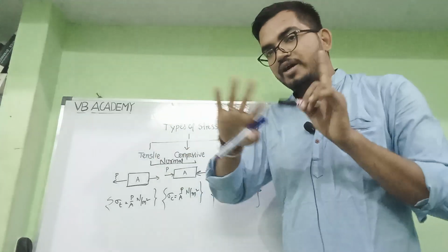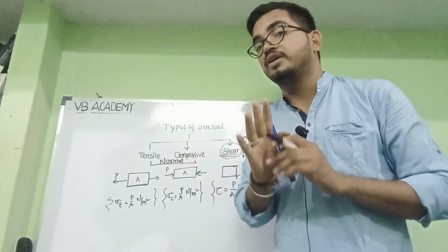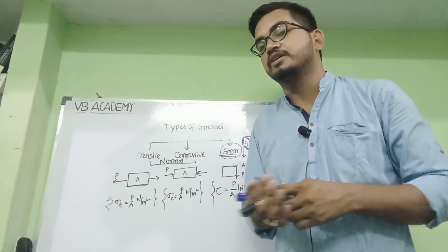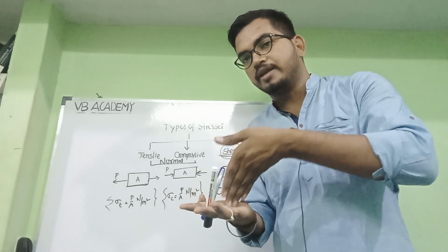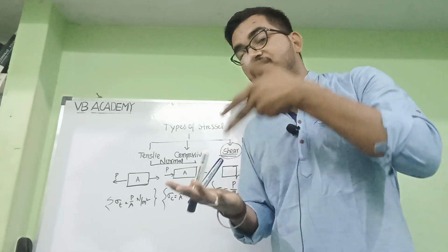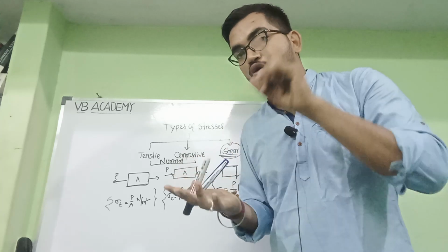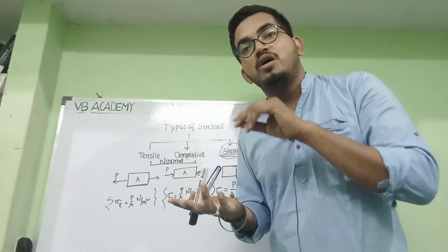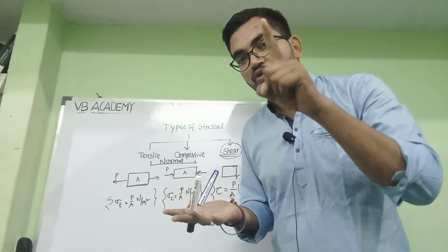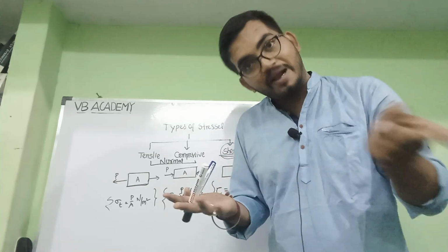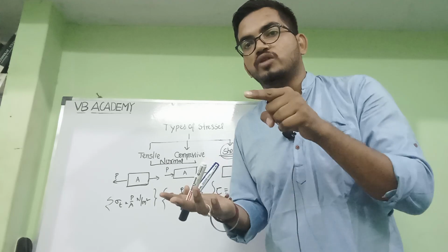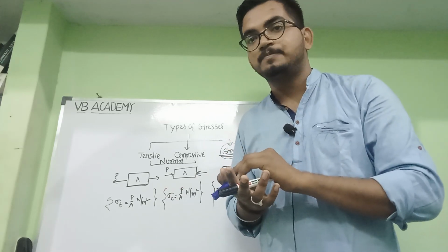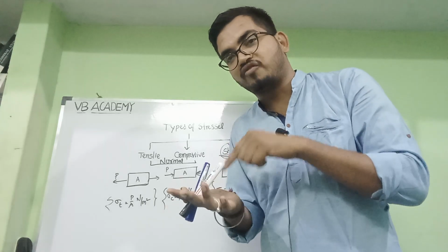First thing, we are dealing with the strength of materials, in which we are going through simple stresses and strain. What is meant by stress? Whenever a load acts upon the body, it resists the externally applied load due to the cohesive forces of the body molecules. That resistance force per unit area, equal to the externally applied force, is known as stress.